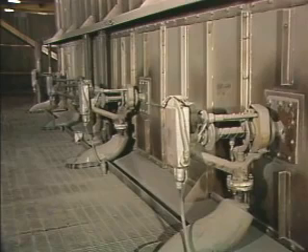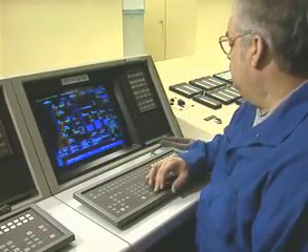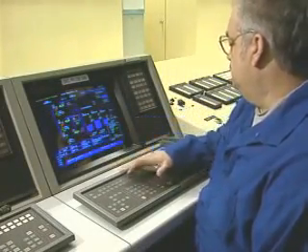To maintain normal operation of a power plant's boiler, the water going into the boiler must be equal to the amount of steam that leaves the boiler and enters the main steam system. Keeping the boiler supplied with the proper amount of water is the job of the condensate and feed water system.